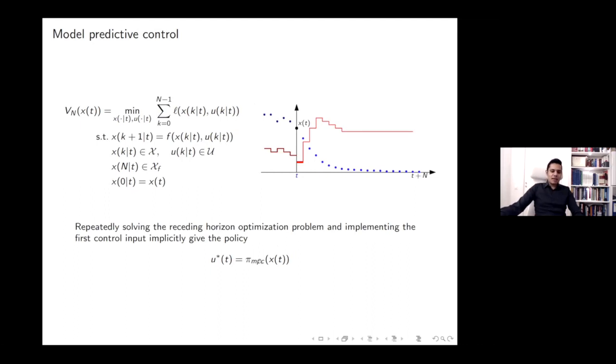Right? And there are several reasons why you may not want to do this. For example, you want to solve this in a much faster sampling time, or want to implement it in resource or memory efficient platforms, like for embedded control applications. And you may not want to solve the optimization problem at each sample time. So what we can do is try to approximate this MPC policy and make a function approximator that can replace the MPC that we traditionally use.